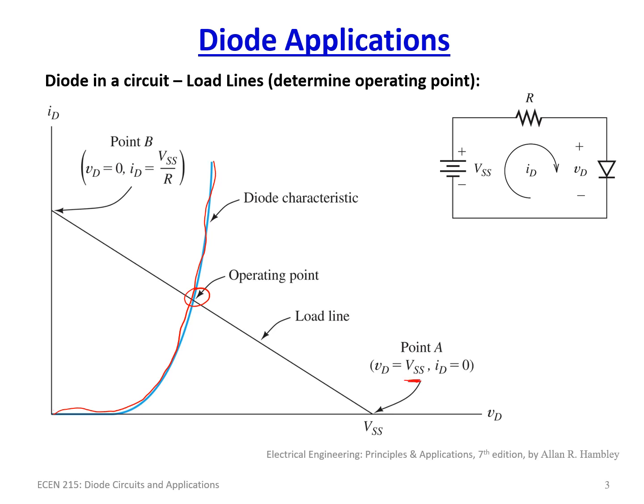with full voltage, VSS, but there is no current. And then over here, VD is 0 and ID is equal to VSS over R. This is simply a case where the diode voltage drop is equal to 0 volts, and we have a current that is just equal to VSS over R, because that's the only thing left, the resistor's voltage drop.